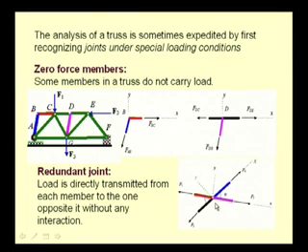But we see that for equilibrium there is no load sharing, that is, the force in this member F2 is balanced by the force in this blue member F4, and the force in this red member F1 is balanced by the force in this pink member, that is F3. So, this joint does not take part in the load sharing. Thereby the presence of this joint is a redundancy and it does not help in load sharing between the members.